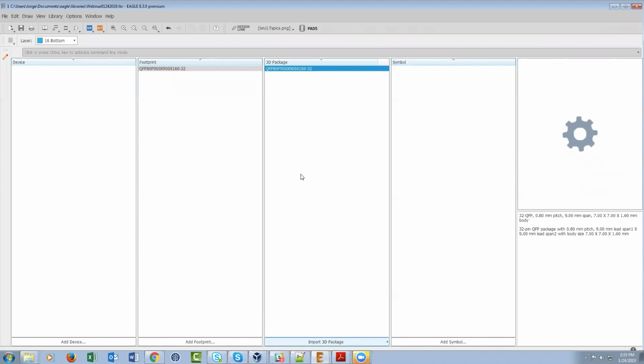But it'll delete it on the cloud? Yeah, it will actually prompt you. You want to delete your local copy, or your local copy and your cloud copy. Oh, sweet. Excellent. So you can basically do everything from Eagle now. Okay, and that's likely how most of us here would want to work.